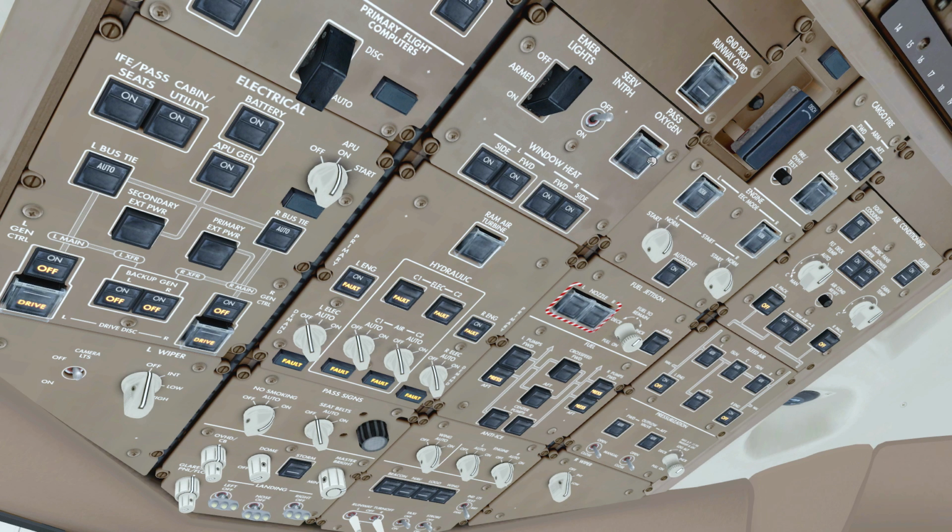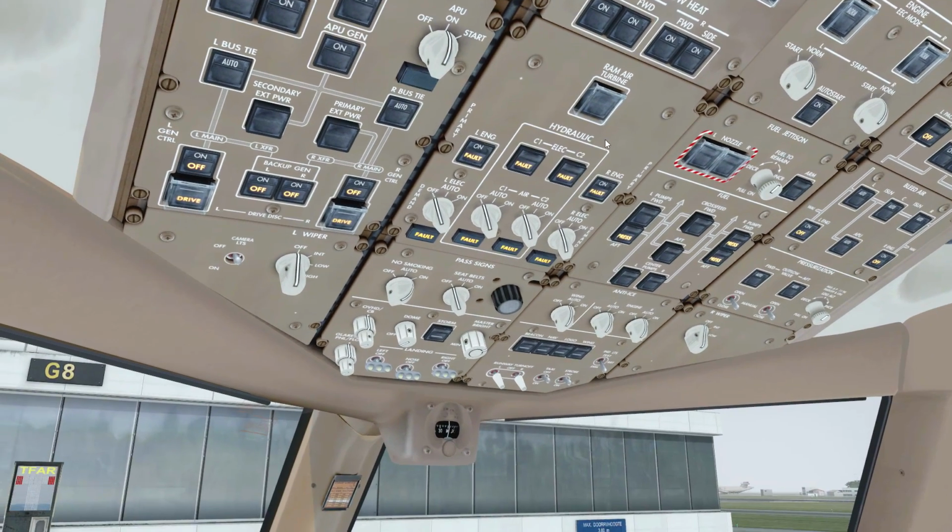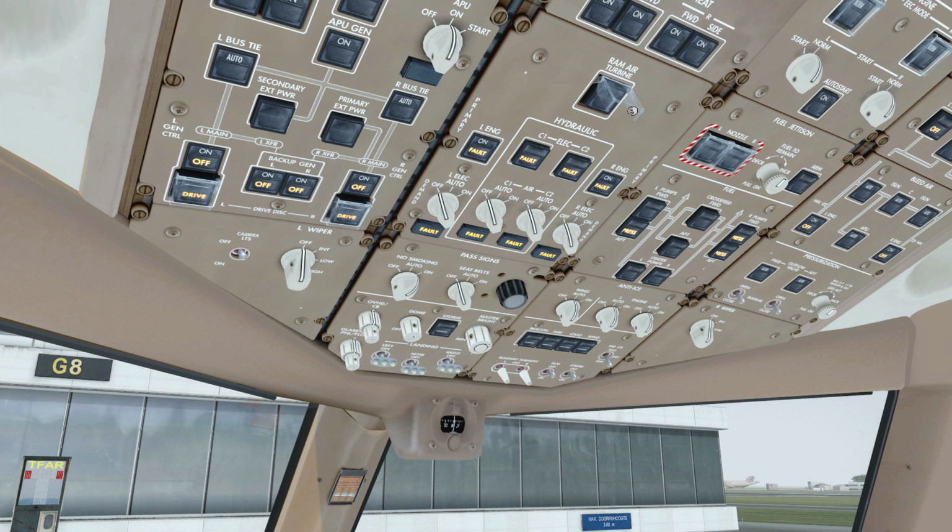Passenger oxygen, of course, also a switch that you don't want to touch. Whenever there's a guard, that's basically a switch that you don't want to touch. This is used to deploy the oxygen masks, so we don't want to touch that. Window heat, make sure they're always on, whatever the weather. This makes sure that you don't build up moisture on the windows, which is of course not desirable, so always make sure they're on. Ram air turbine, also make sure the guard is closed. This is deployed once both the engines fail, providing some main hydraulic and electrical power to the aircraft in case of an emergency. So just leave that closed.